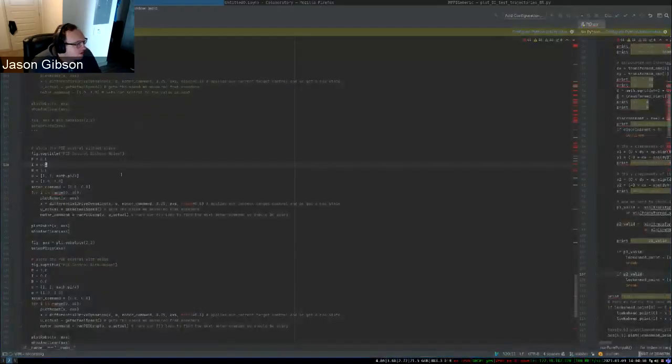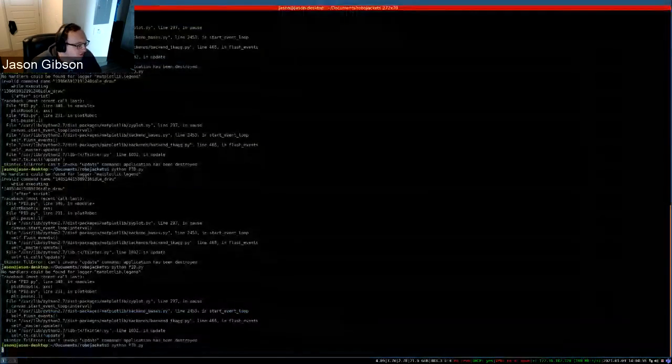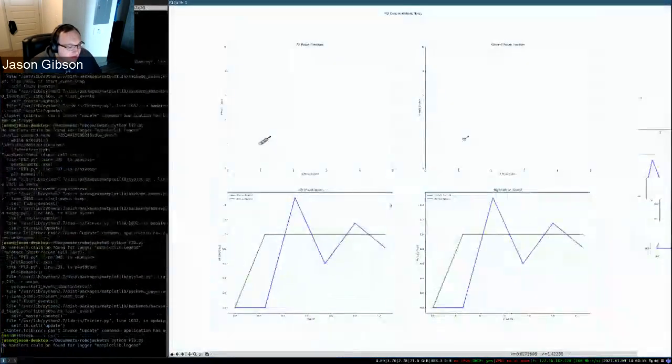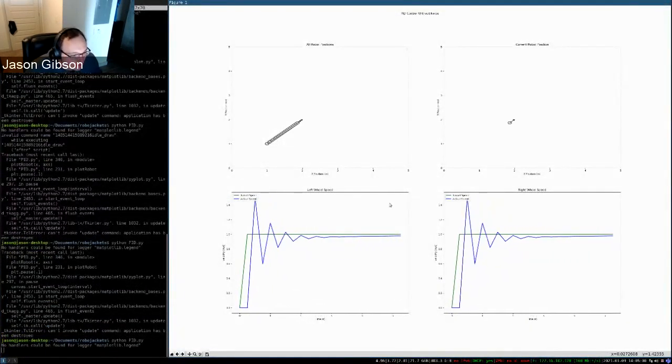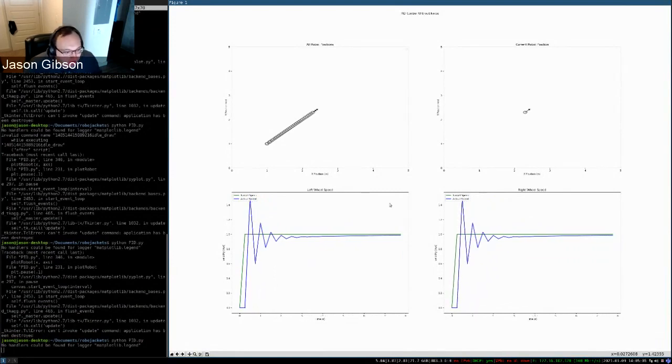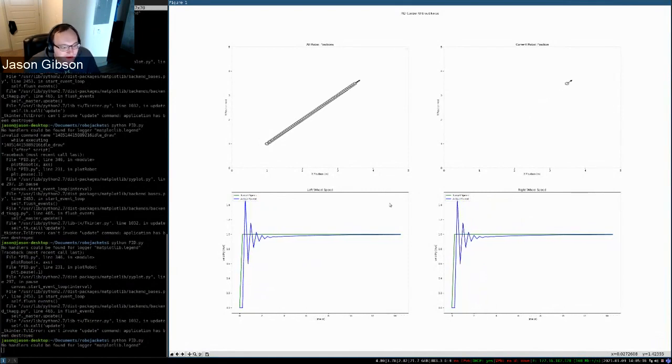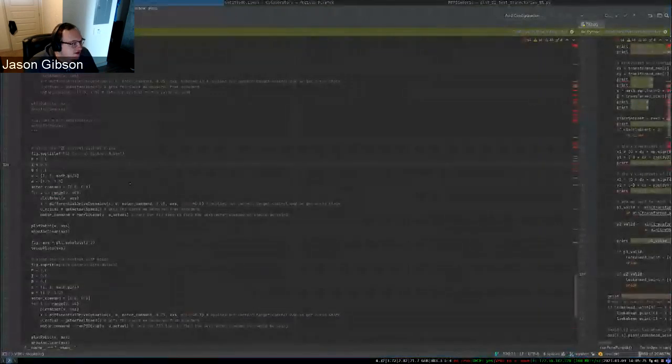So we're going to go for a higher I, 0.5. That was getting rid of our steady state error, and now we'll probably do even better. Now you can actually see the two lines are converging. And again, with all things in control systems, it all depends on what you're looking for and what your goal is. This could be a really great tuning for my PID if I was doing something more safety critical. But if I was doing something more aggressive, probably for what you guys are doing, you'll want a little bit faster convergence.